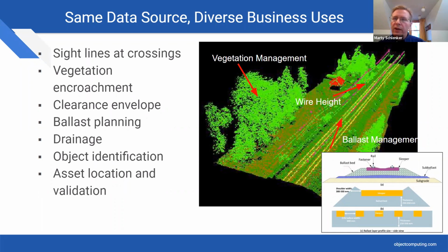And that's for good drainage, so that the ballast remains supportive of the ties, even as trains pass across the rail route every day. And so making sure that the drainage ways adjacent to railroad rights of way are always kept clear, and that opportunities for water to pool and infiltrate the subgrade are addressed, is an extension case from the ballast management case.